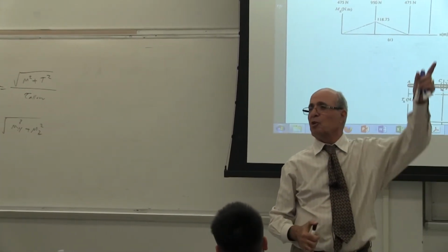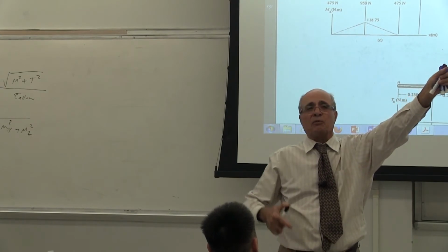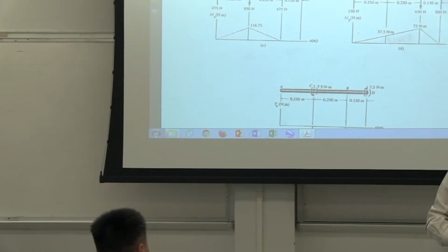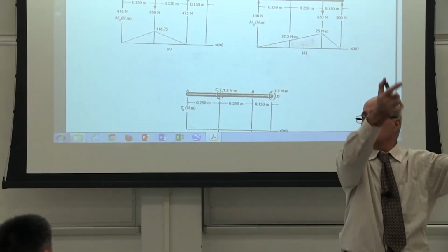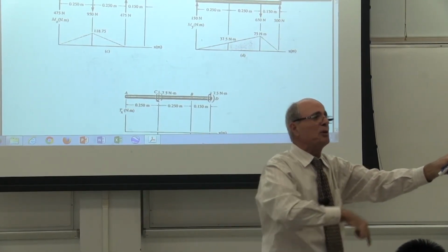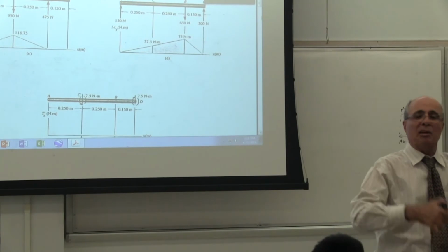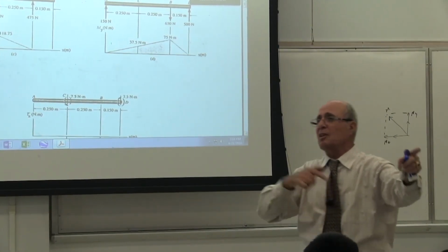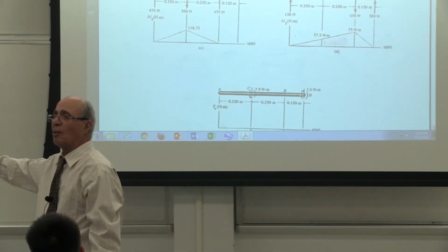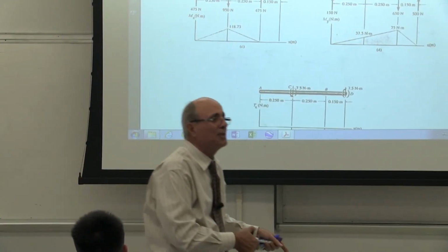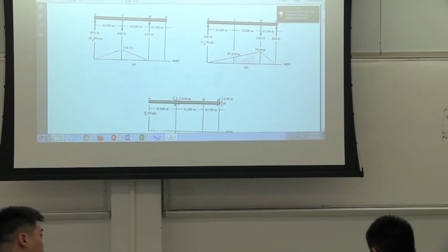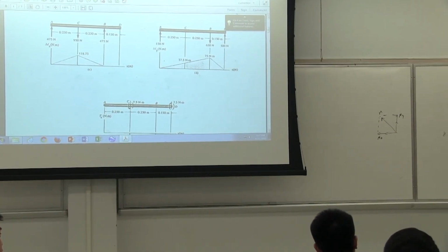That's the magnitude of your moment vector, yes or no? Look, from statics through ME218 and ME219, we took the vector and divided it into components. Then we decided which one creates bending and which one creates shear stress. Then we found shear stresses, moment stresses, all of that, and went through the Mohr circle. At the end, for this equation, I don't care which one is torque and which one is bending. All I need is the magnitude of the moment, regardless of which one is torque and which is bending, everybody.